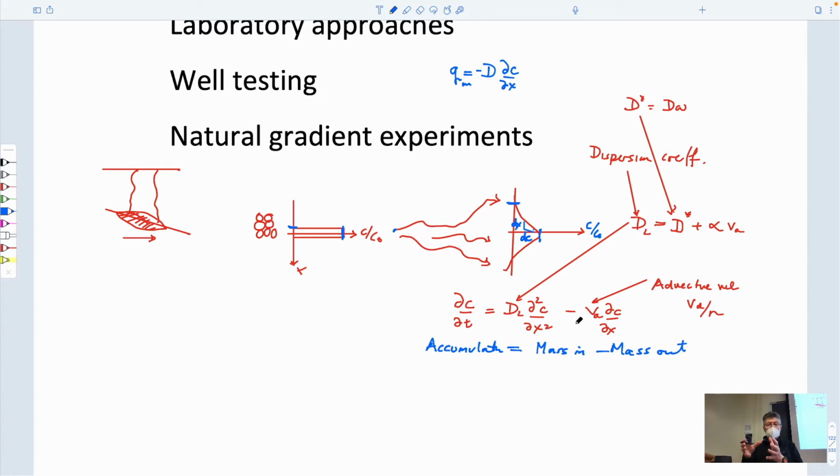So it's carried on the carrier fluid, which is water, and also a diffusion process whereby the mass is transported by its own potential, if you like. It goes from high concentration to low concentration. This is a very slow process. This is a very rapid process. In granular reservoirs, this is large, and this is trivial in comparison. And in clay reservoirs, this is tiny, and this is large in comparison. So they switch roles, depending on the media we are in.